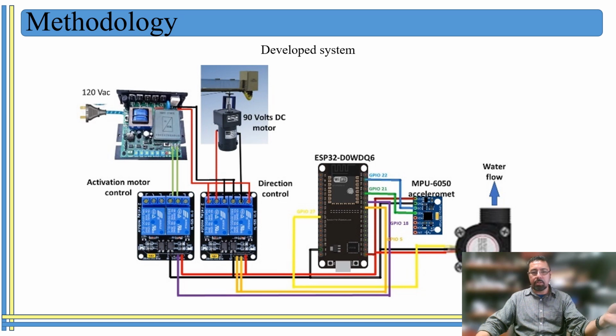And then this motor is connected to a set of relays which are going to indicate when it starts and turns off, and whether it turns in one direction or the other to start lifting the shaft or putting down the level of the canal. And we're using an ESP12 board to have the wireless connection, and it is the main board that controls the whole system.